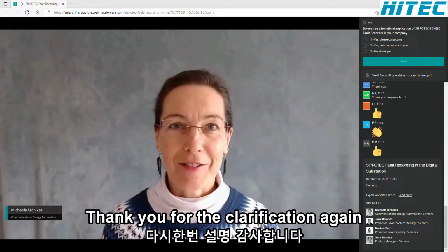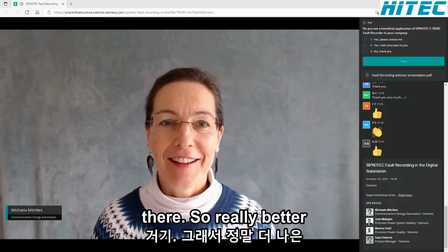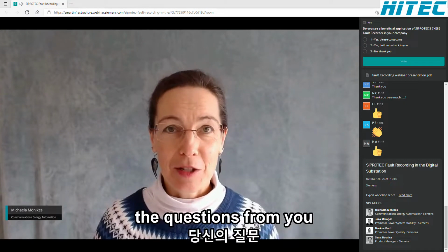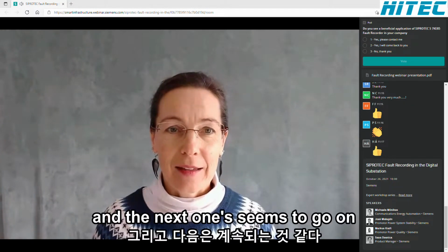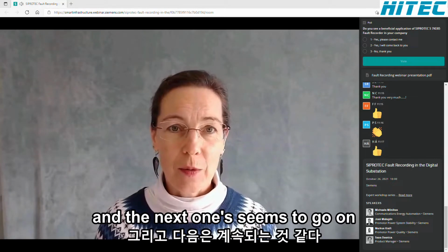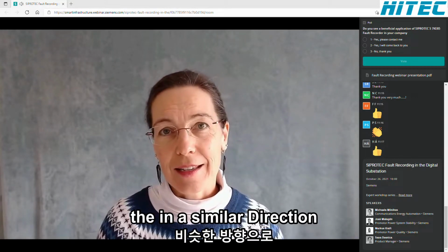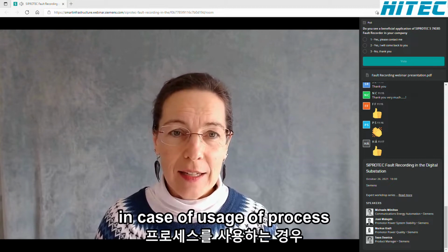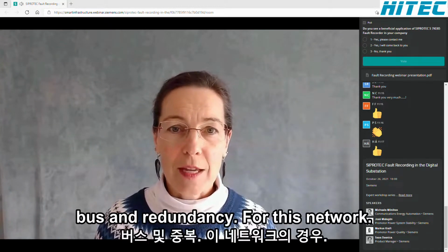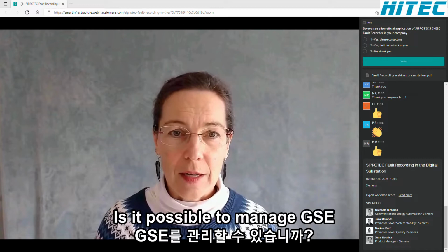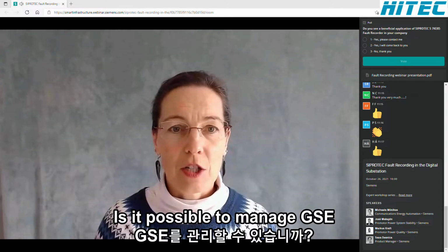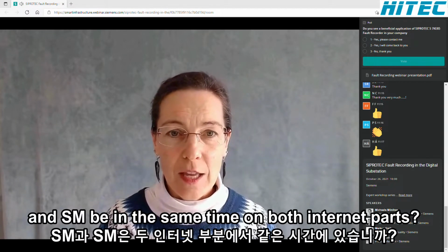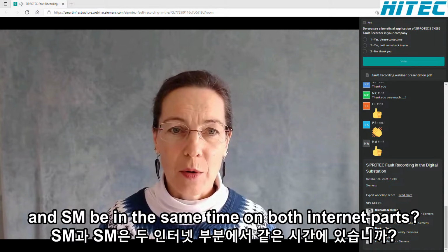Okay, thank you for the clarification again there. So really valuable questions from you. And the next one seems to go in a similar direction. In case of usage of process bus and redundancy for this network, is it possible to manage GSE and SMV at the same time on both Ethernet ports?